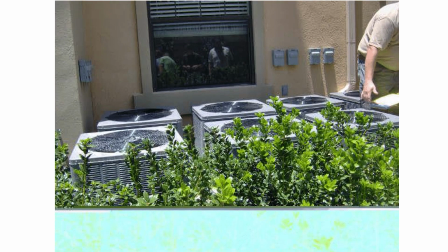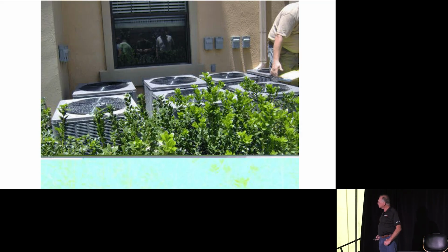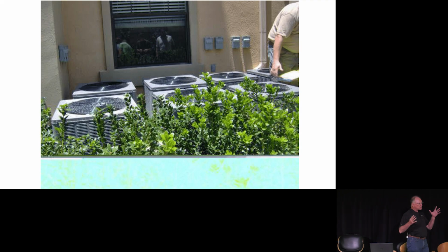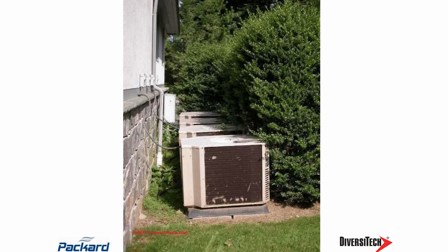So if I look at this unit, is there anything that might impact the static pressure? No problems with that, right? Is there anything that would impact the static pressure on that? Yeah. And if it's pretty close to the wall, that could impact my static pressure as well. And I like how we have those connections right up there. That's nice and convenient for the kids to play with. But as we add static to that, that's going to put more load on this. It's going to result in less air too. How about that?